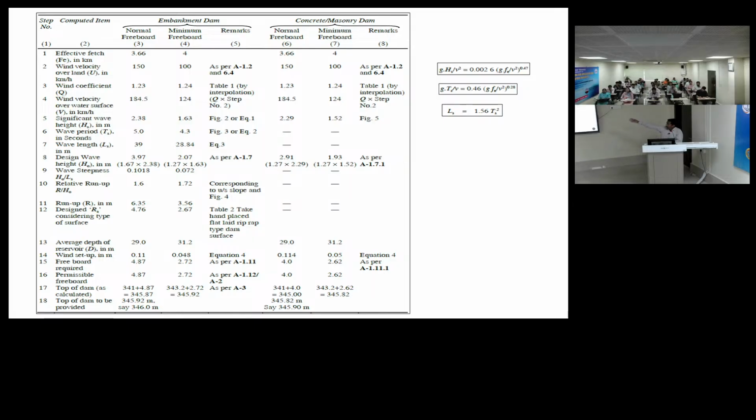In the normal condition, that is a regular condition, we are taking the maximum wind velocity of that area, and we are reducing it to 2/3 whenever we are considering MWL calculations. So that is the basic difference only, remaining steps are all the same.